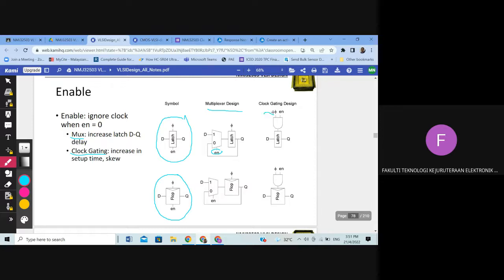This is normally the clock, CLK. We have the clock running non-stop normally. But if you don't enable the clock, this is an AND gate. So if you give 0, this is the waveform of the clock. Sorry about the diagram. If we give 0, with the clock at 1, 0, you get 0, because it is an AND gate. 0, 0 also gives 0. So towards the end, you will get 0. But if we give 1, let me use a different color.